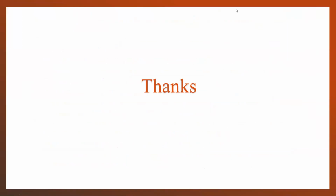So this was all about the two experiments, pulse width modulation and pulse code modulation. In pulse code modulation, we have seen the sampled waveform and the quantized waveform, observed the quantized and sampled signals in the CRO, and seen how an analog message signal is converted into digital form. We have also observed how PCM signals are generated, transmitted, and received or decoded at the receiving side. After that, we observed the pulse code modulation sequences on the CRO. I hope you all have understood these two experiments and their related concepts. Thank you.